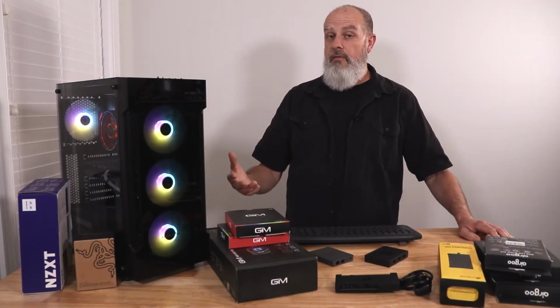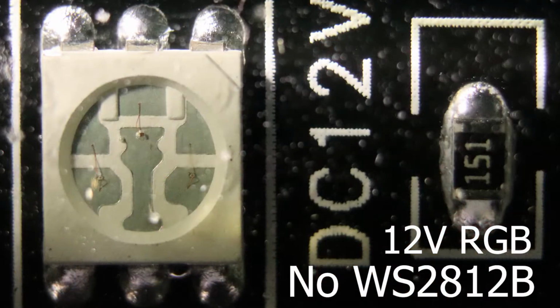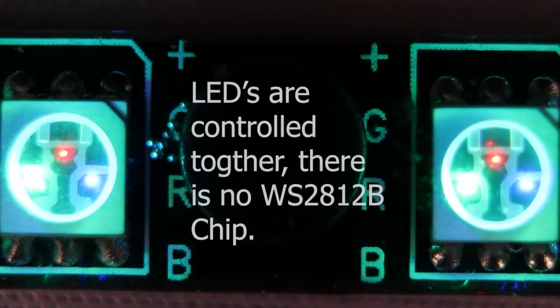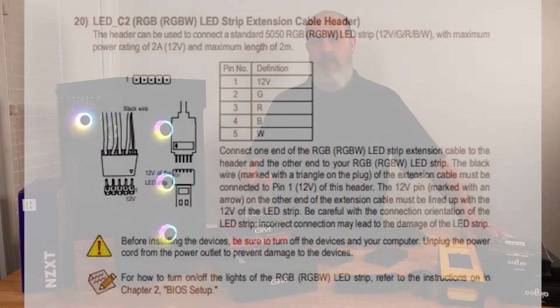And so the other type of RGB out there, I'm just going to call it 12 volt RGB. What that means is that there's no individual controller in each LED, meaning that you can control the strip as a whole. It's got a different connection, which we'll go over in just a second, but you're basically just adjusting every LED at the same time. So the whole strip can be red, the whole strip can be blue, but you can't talk to each individual light.